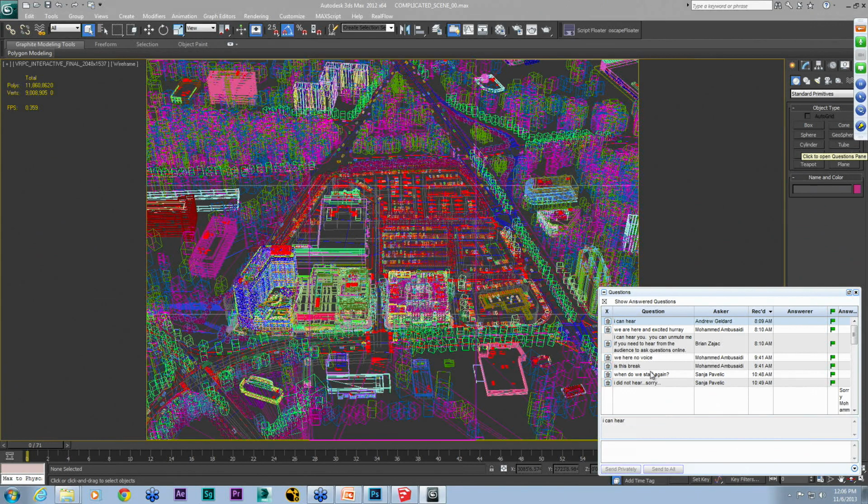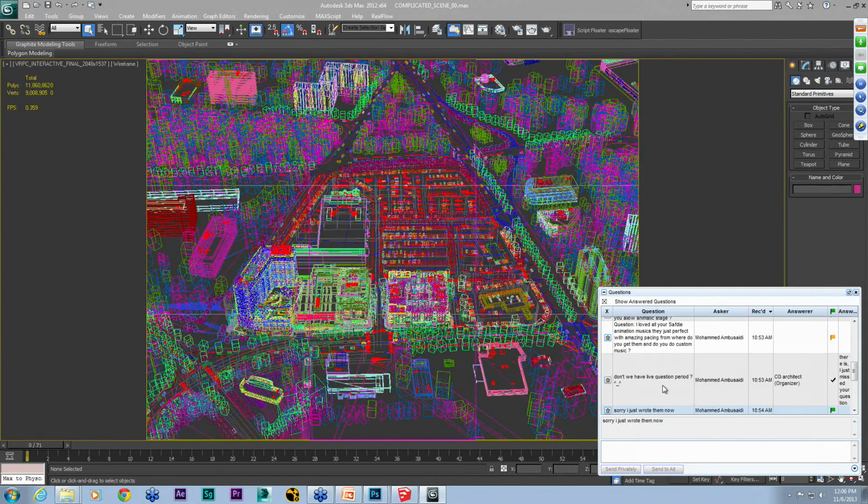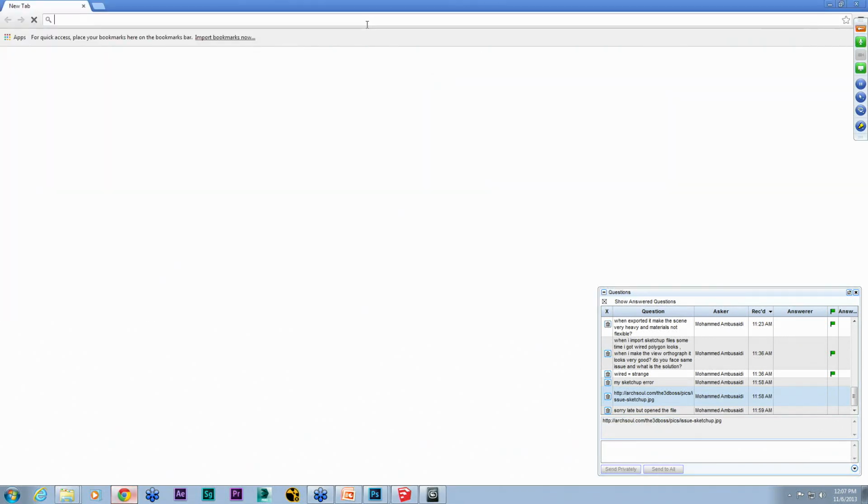Yes. One of the other things you can do with Deadline is render distributed through Deadline as well. It's called Force Workstation mode. It allows you to essentially open an instance of Max like you are distributing on your machine, as long as you set up V-Ray correctly and set up your nodes correctly. Do a DR in a radiance map then through Deadline. Yes. And then you can set the priority as well for your tiles.